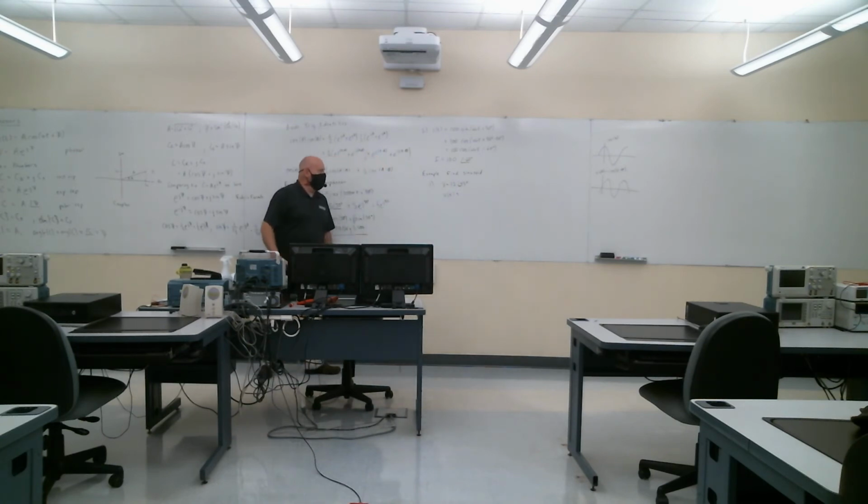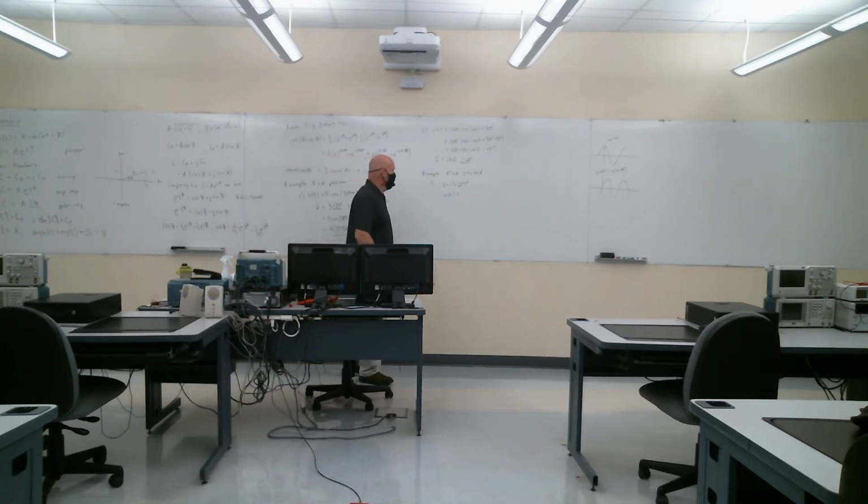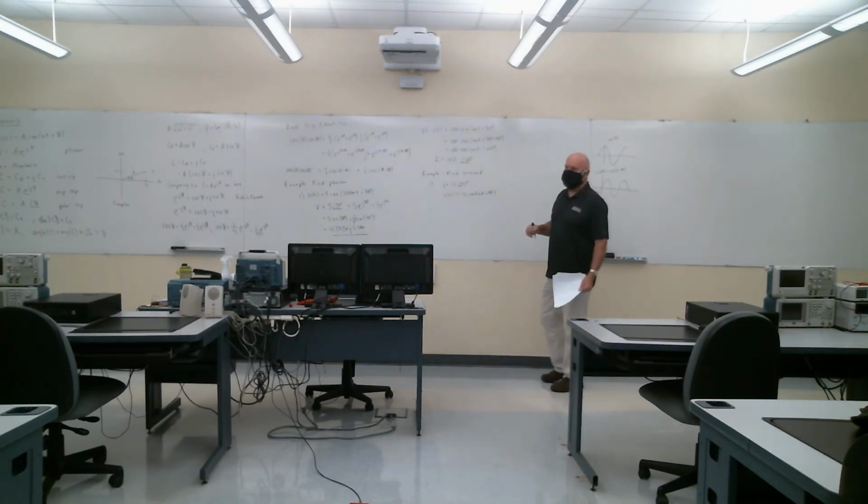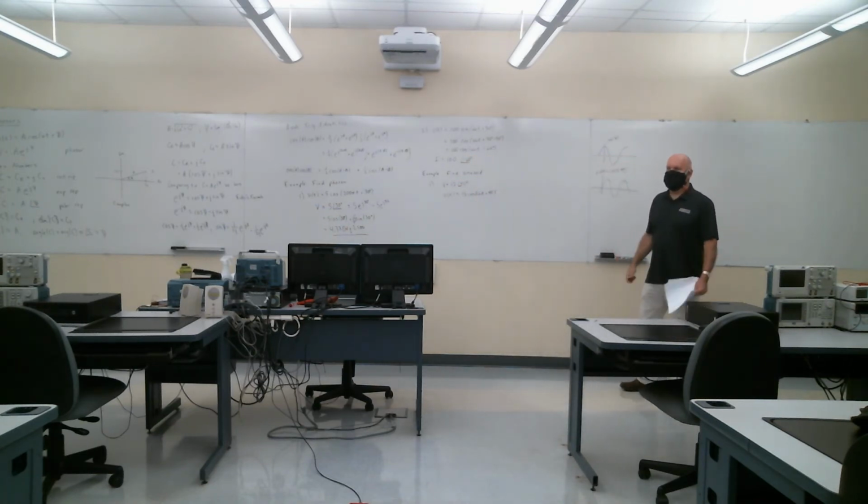So what's the corresponding time domain expression with the phasor in that form? Well, in polar form it's simple, right? It's 12 cosine omega 0t plus 45 degrees. I didn't give you the frequency, and you have to know that it has to be given in order for us to actually sketch what the corresponding sinusoid is.